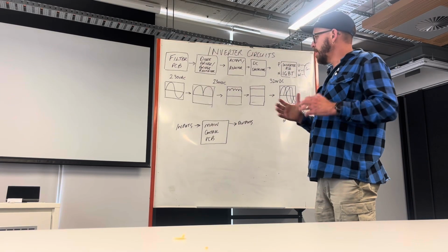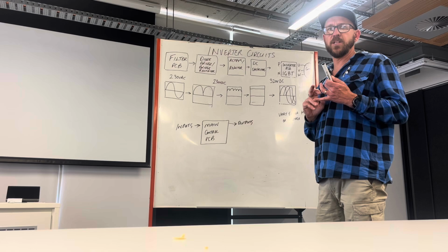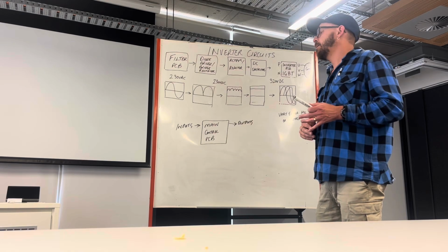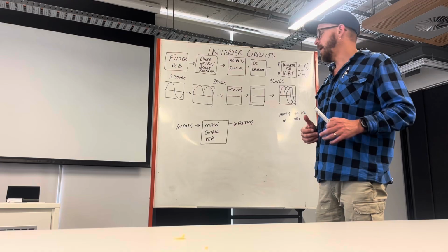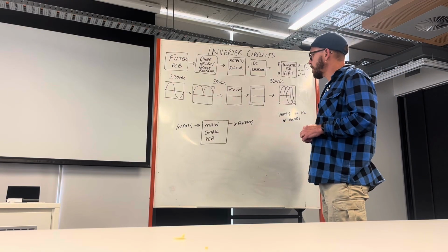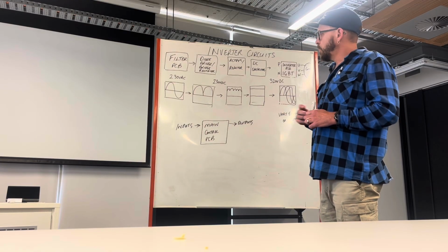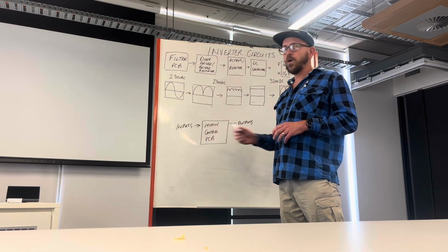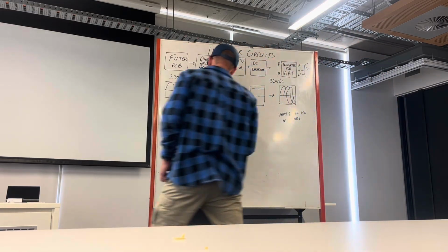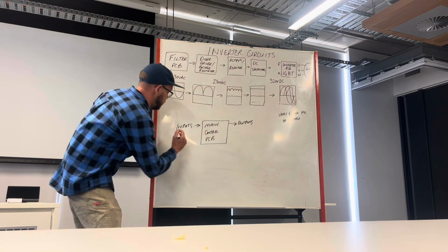Now, inputs for a control board can be things like thermistors, signals from the indoor unit, from the wall controller. Perhaps there's external inputs that have been connected to the unit. Anything that's telling the control board what's going on. So thermistors, pressure transducers are important.